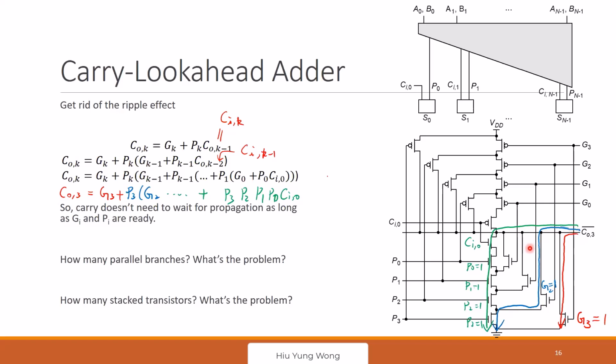P-value, I put in the solution, but maybe not clear. But to find the p-value is that you size the transistor so that you have the same resistance as the inverter, and then find the drain capacitance, right, as the intrinsic capacitance. The drain capacitance depends on how many transistors you connected to the output.